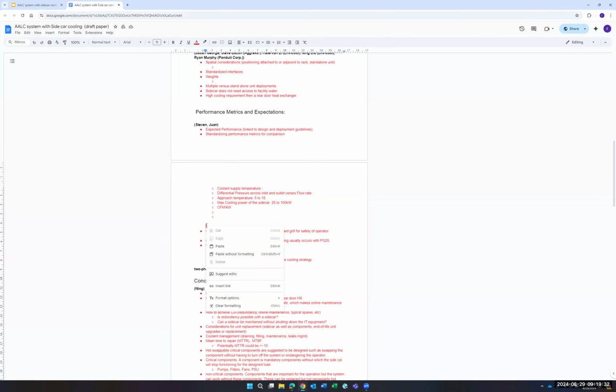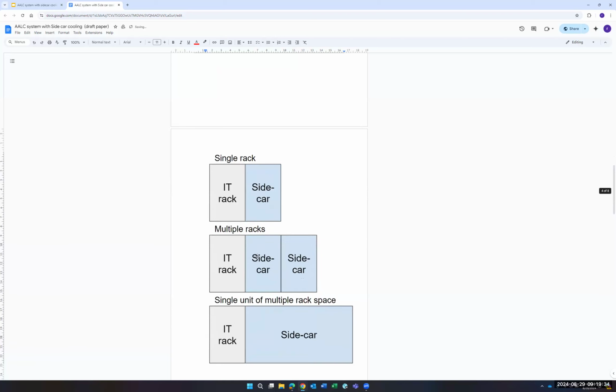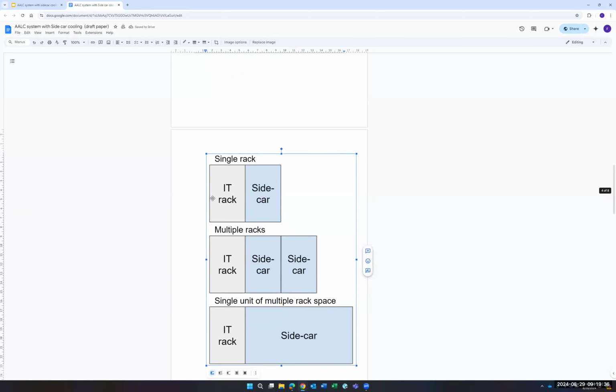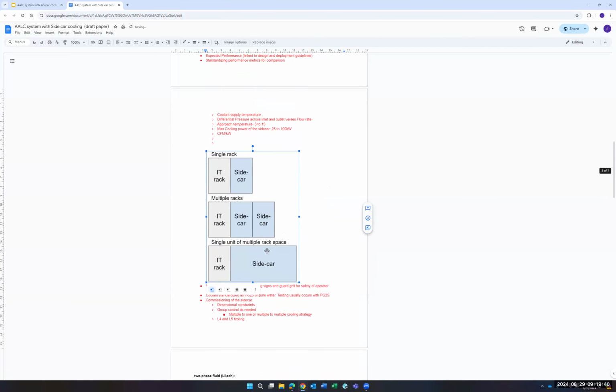Right. So that's my point, that there's an upper bound on the maximum cooling capacity you can get with a rear door heat exchanger because of a lot of factors: the size of the heat exchanger, and, as you're saying, the volume of air you can effectively get through the server. So I think the comparison should be, what's the upper bound you could conceivably have on a rear door heat exchanger?